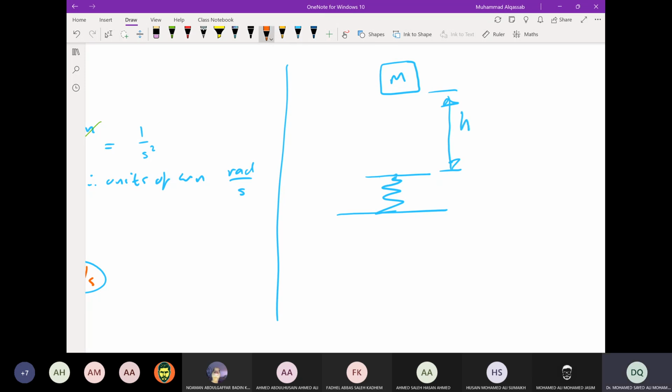We take this point as point number 1, and the second point is when the spring is under maximum deflection. This is point 2. And then we can find this distance, we call it x, for example, capital X. So what you did in dynamics is relating point 1 and point 2 only. And the reason is to find the maximum deflection of the spring when the mass drops on the spring. So we let the velocity equal to 0 and we apply conservation of energy and so on, right?